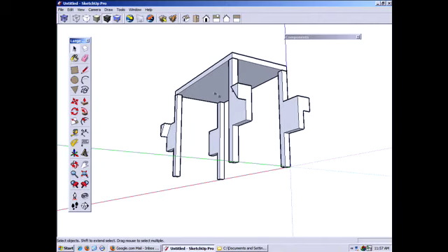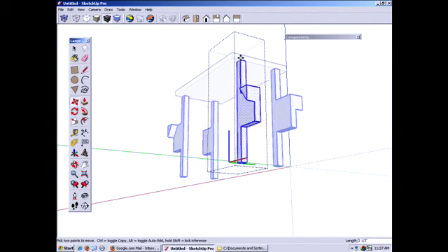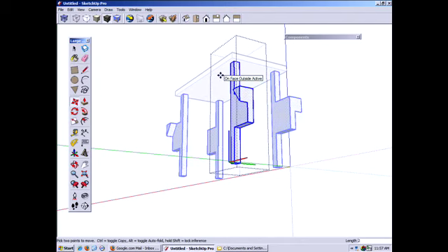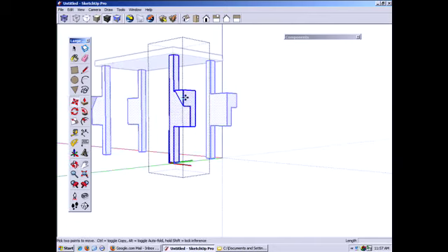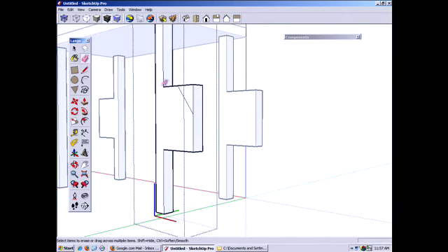So what I do now is edit one of these components, select it, and with the move tool I just move it in, say 2 inches, and move it back, say 2 inches. Very, very easy to do. Very nice. And now we can get rid of this sort of ridiculous outgrowth that we created. So I'll erase that.